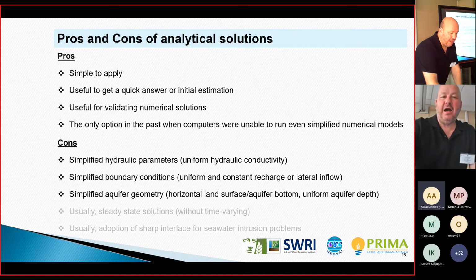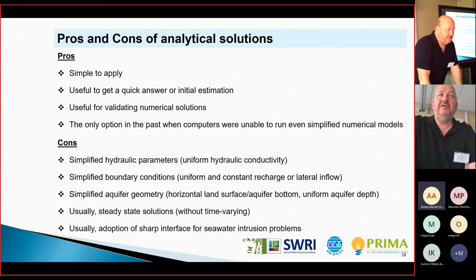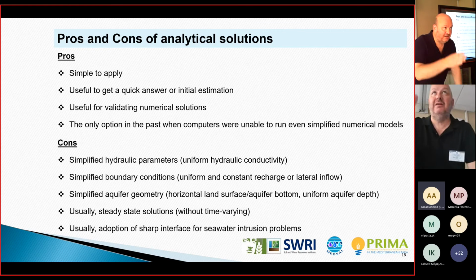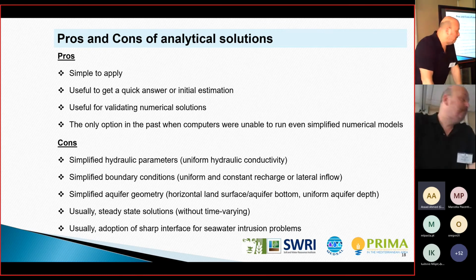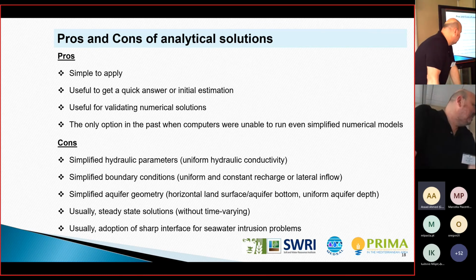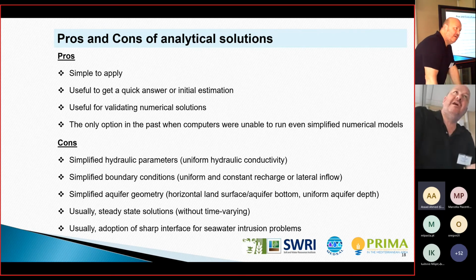So we have uniform aquifer depth, and usually the solutions that we take are steady state solutions. So we take just the solution for each problem. We don't have the variation of time. And usually it adopts the sharp interface approximation, as we said before, although there are some analytical solutions that use the transition zone approach.